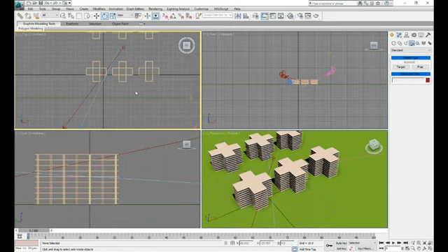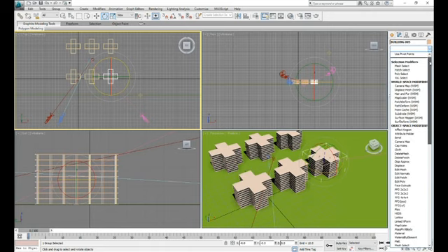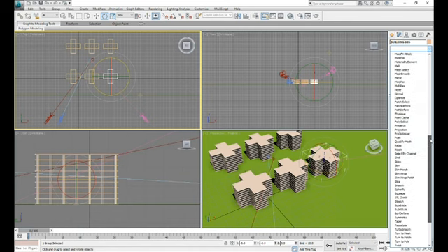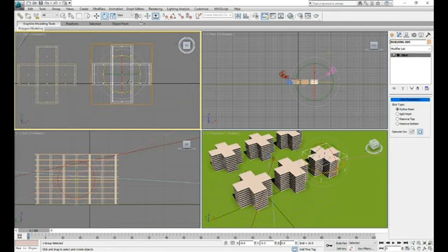Now, when it comes to 3ds Max, there are a lot of secrets. I'm just showing you the best figure that can be done in an easy way. But for some of the other complicated things, we have what we call the modifier list. For example, I will select the third building, this one. What I will do in the modifier list is slice. This is what will happen. I will create the slice plane.